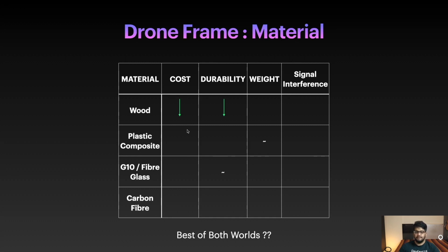For example, if your drone arms break, on the arms you have mounted your ESC, there may be ESC wire breakage, and because the battery is connected, there may be a short circuit, and your entire electronics fry, and the magic white smoke comes out, and the possibilities are endless. So do also keep in mind that durability is not just the frame durability, but also the housing, the shell it provides to other components.